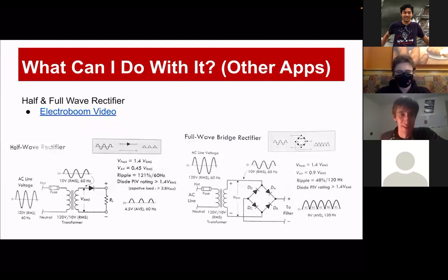But the half-wave rectifier here takes in an AC voltage, yeah. So we have a sine wave going on. And our goal is we want to convert it into a DC voltage. So instead of a sine wave oscillating between positive and negative, we want just a flat positive. And we get there a little bit when we do a half-wave rectifier. So whenever it's positive, it's allowed. And then we get down, and negative is not allowed. So we have just 0, and positive is allowed, negative is not allowed. And we continue forward like that.